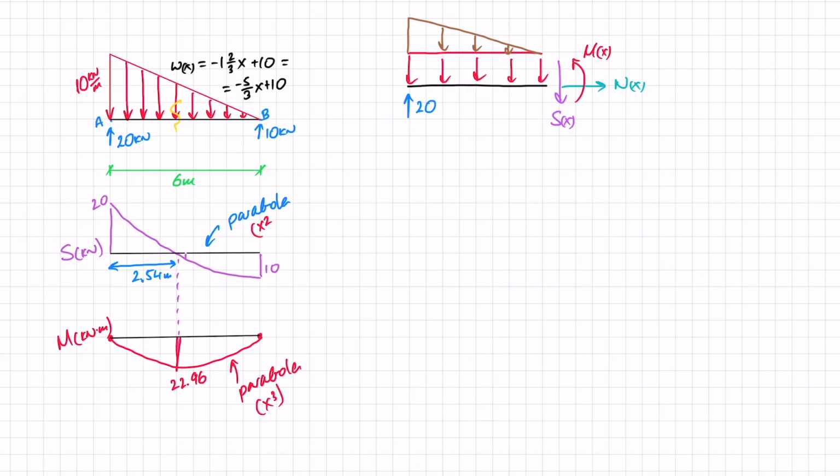So looking here at my forces, you can see that I've just divided this into two shapes. And the reason that I've done it is really because I find it really easy to remember that the centroid of a rectangle is in the middle and the centroid of a triangle is 1/3 and 2/3 from the opposite side. And that just makes it slightly easier to remember. Obviously, if you remember the trapezoid, good on you. Let's do it this way quickly to validate the results that we've already received.